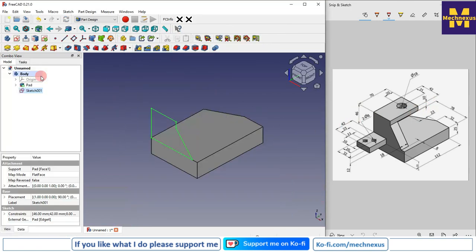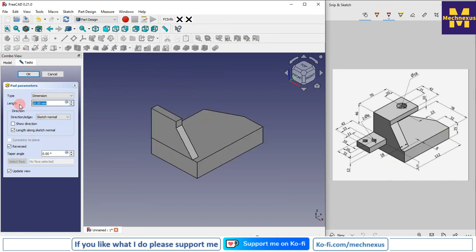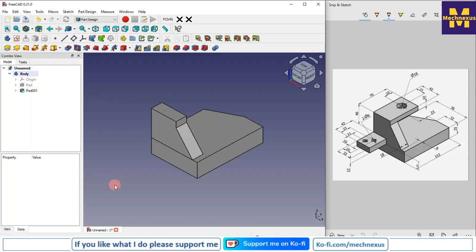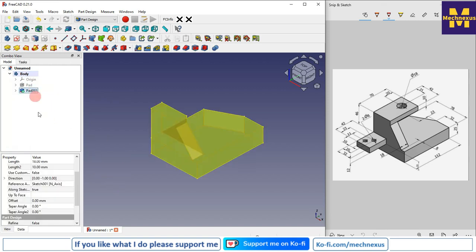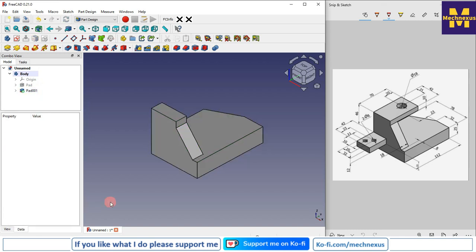Now we will close this sketch, click on the pad and give the pad of 18 mm which we can see here. So click on reverse and give the 18 mm, click on close, and now you can see here these two features are not merging. So click on the pad, set here refine, set it true.